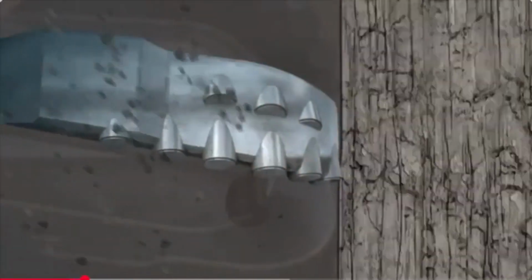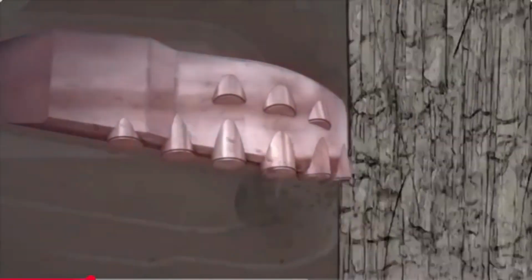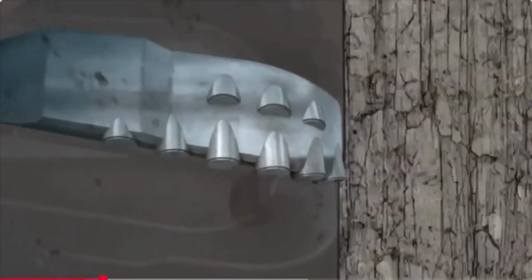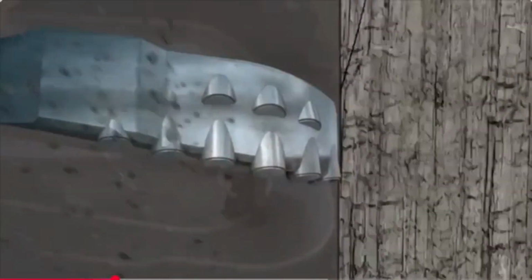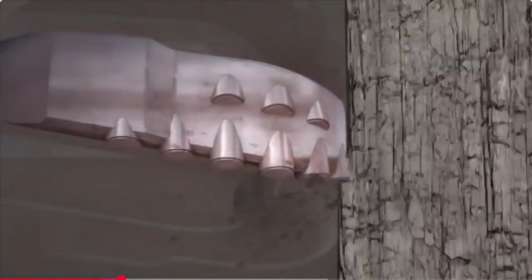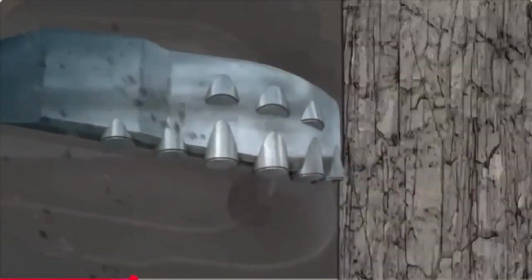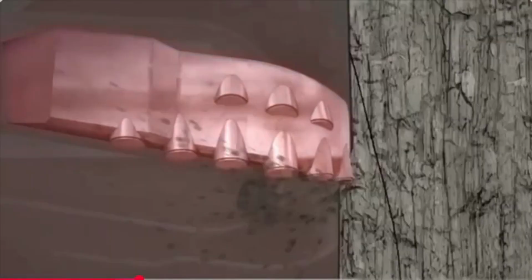However, in changing formations, this remote application of forces can easily contribute to sticking or stalling. The buildup of torque following a stall will eventually cause the formation to break, and the bit will spin out violently. These instabilities are known to be the source for severe vibrations, equipment failures, and slow and costly drilling operations.